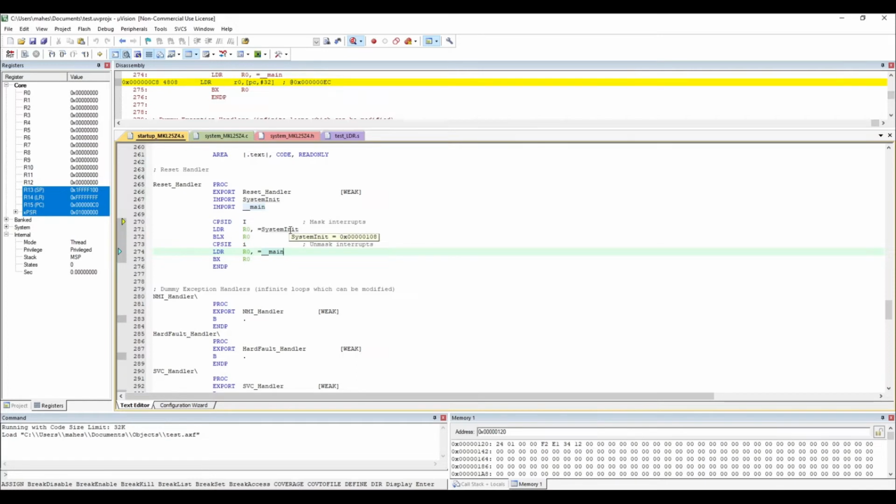When you discuss interrupts, we do have a separate session about interrupts. That time you will understand what is a maskable interrupt and what is a non-maskable interrupt. But just to give you a feel, non-maskable interrupts are critical things that you want to execute. For example, the temperature got increased and you want to shut down the system. That cannot be postponed, right? It has to be immediate. So those things cannot be masked. But there are certain interrupts which are user-defined interrupts which can be masked. So those are masked.